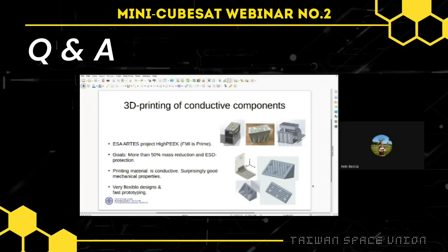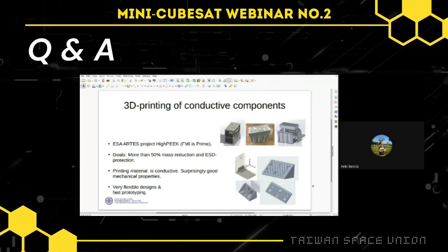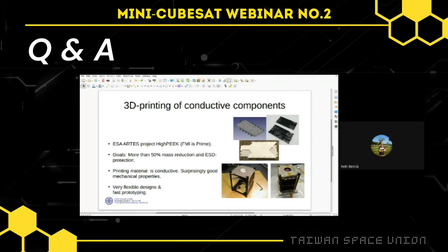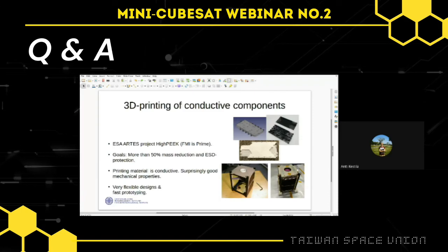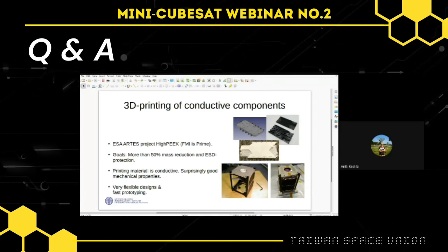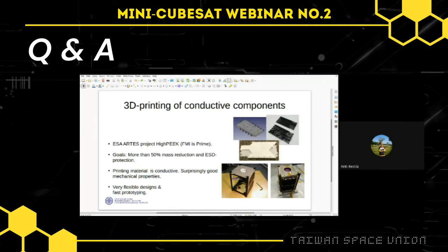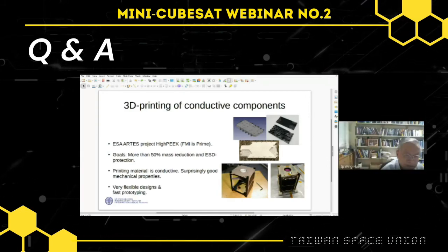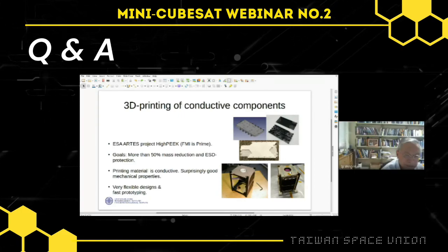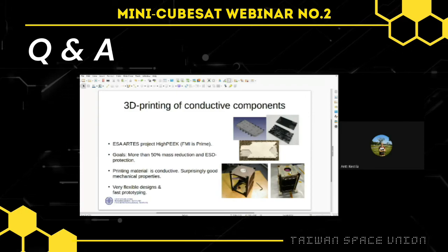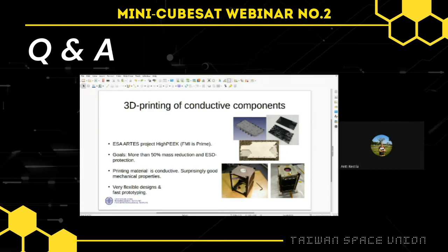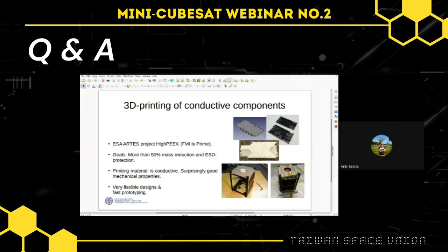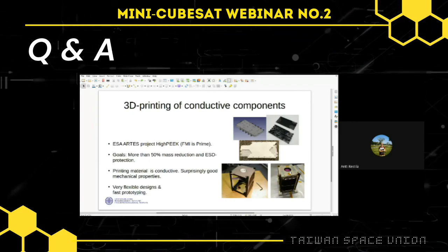Yeah, definitely. I've understood that NASA is too, and I would recommend it. Maybe the one downside is that you have to be a bit careful about the thermoplastic material. For example, in this image, the material is called Aalto, which is the trademark name. I don't remember the actual chemical name, but as you can see, it's very close to the camera. If it's a bad type of thermoplastic material, it might outgas, so you have to be careful about choosing the material if you have lenses, so it doesn't coat your lens and ruin the view. I'm not sure these materials are appropriate for really sensitive imaging instruments. Even PEEK, which is really good in terms of thermoplastic materials, has a bit of outgassing, so maybe it's not appropriate for all kinds of instruments.